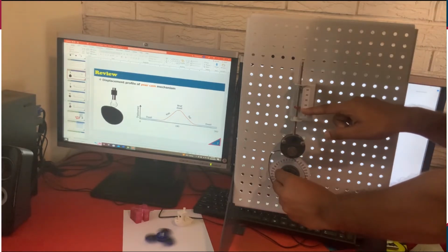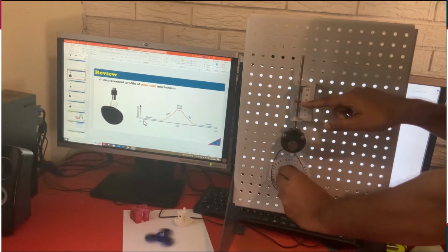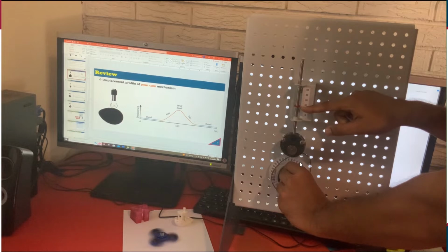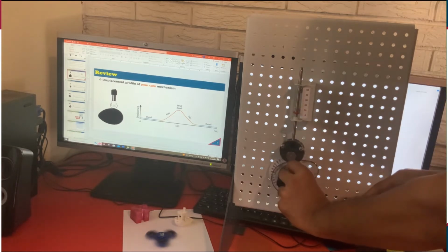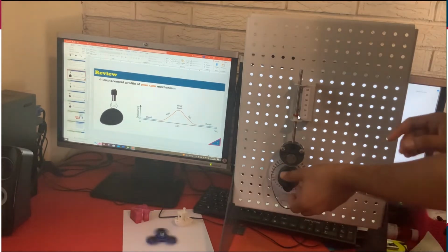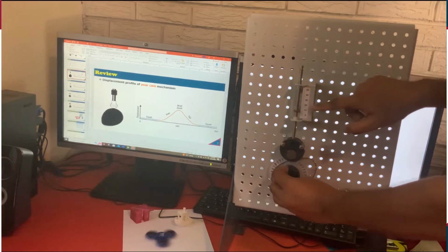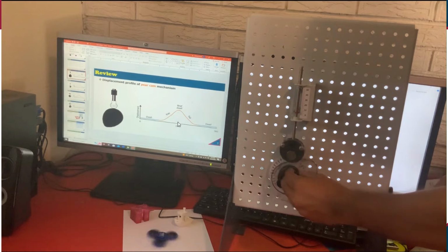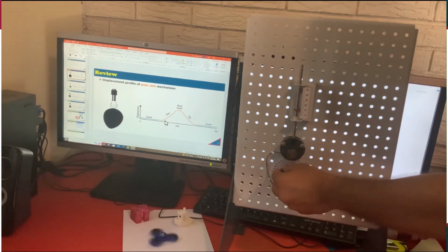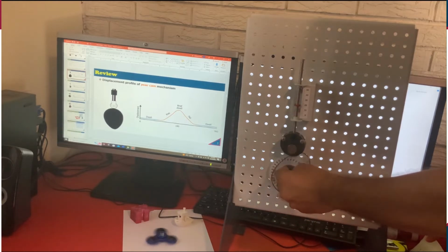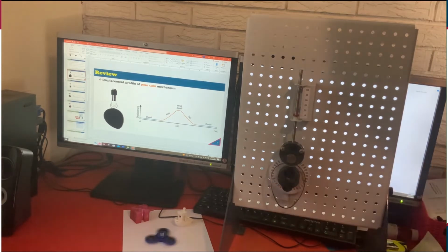So what you have to do is create a similar displacement profile that should look like this at different angles. So maybe at 0, 20, 30, 35, 40, 60 different angles, you have to measure how much the displacement is and record the data. And when you plot them, you should be able to get a similar displacement profile for the pear cam. And now in the next slide, we're going to see what data we have to collect.